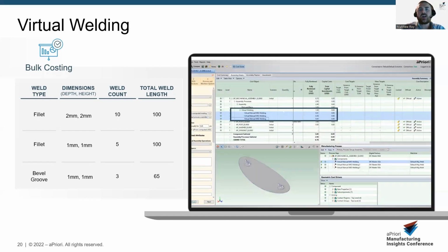What this does is enable us to add 18 welds in far, far fewer picks and clicks, with much less margin for improper assignment. That includes wrong edges selected, too many edges considered part of a weld, and inappropriate size considerations that the traditional weld tool might use. You might lose a bit in terms of fidelity of results, but you more than make up for that in throughput.